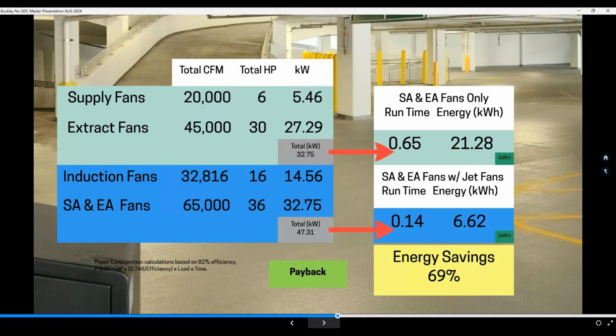And this is the intent and the design goal behind the International Mechanical Code, implementing the ability to reduce the continuous maximum ventilation rate from 0.75 down to 0.05 if you tie to gas detection, because you're creating a demand-controlled ventilation system.